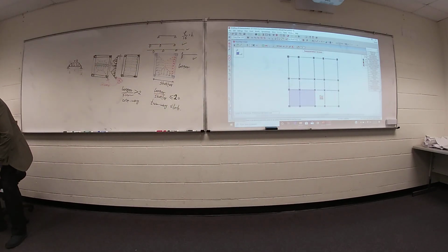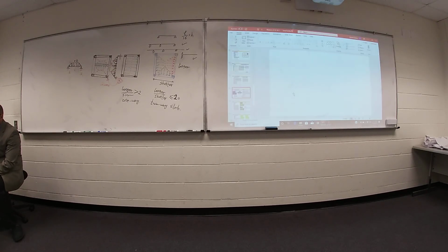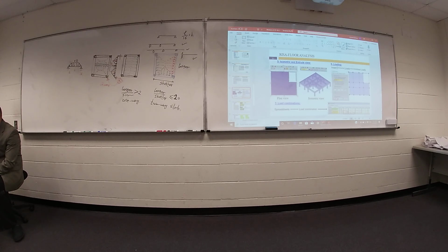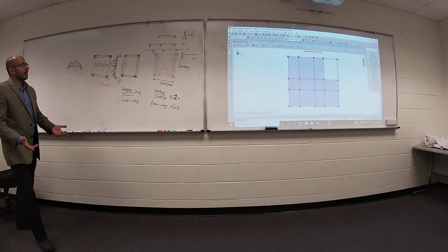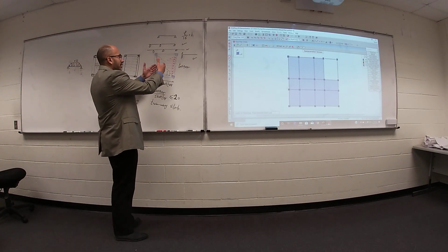So go ahead and define your live load. Just click. Don't do anything here. We defined our load. So loading, insert, loads, area load. Choose your type, click this one and apply. Just click at each panel, you can define your live load. Once you defined your load, you put your load on a slab.